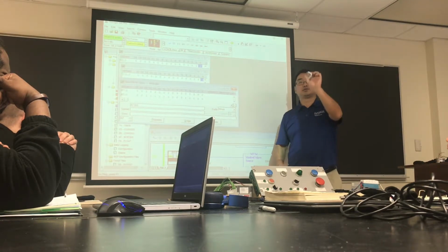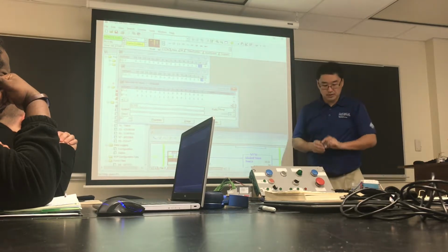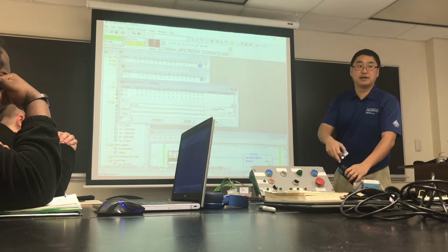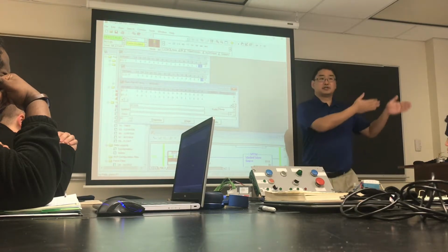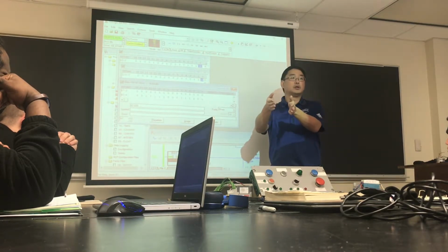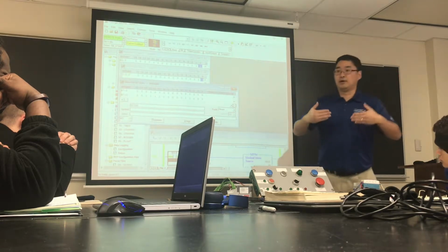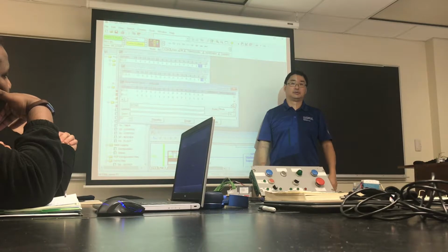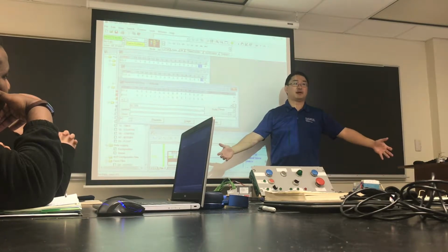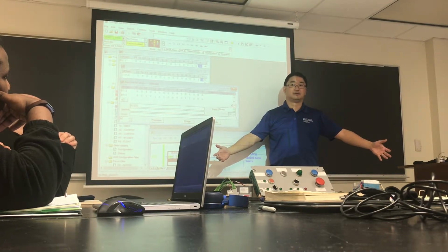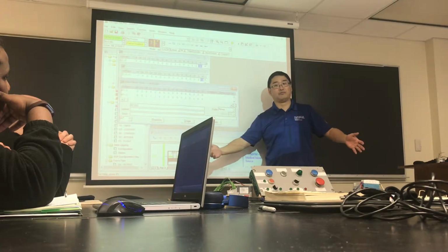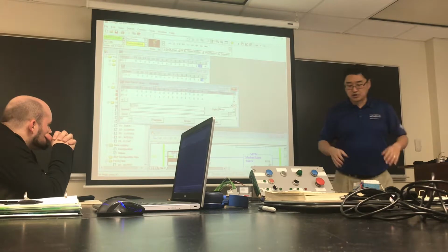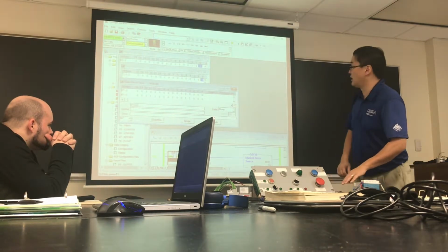Because I've got 2 set screws in here, and remember there's 4 sensors in here, and the set screws are spaced off of the sensor. As that goes past the sensor, as it comes even up to line up with the sensor, I'm getting different values. Which value is correct? Well, it should be the last one, hopefully, but that's what I have to be careful of. And that's where that one shot can potentially come in and help out.